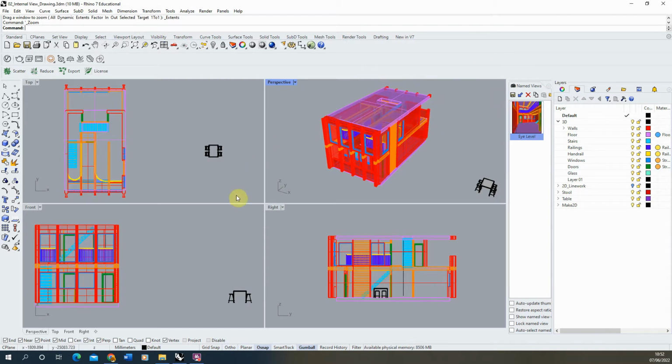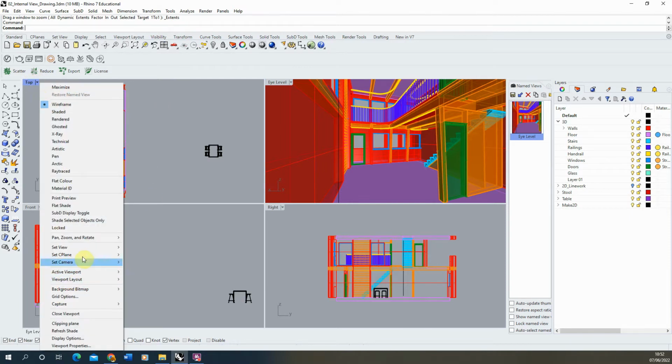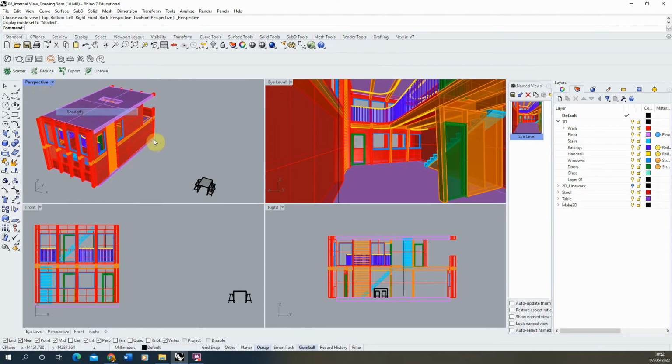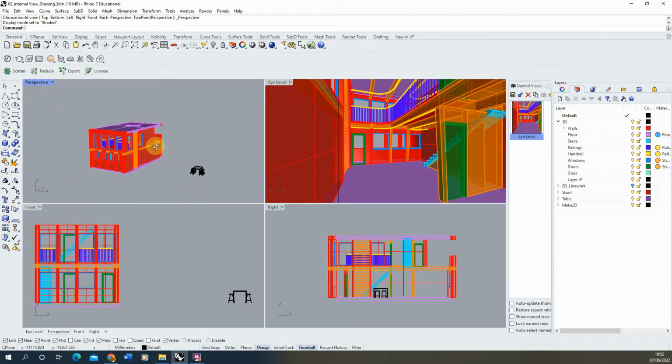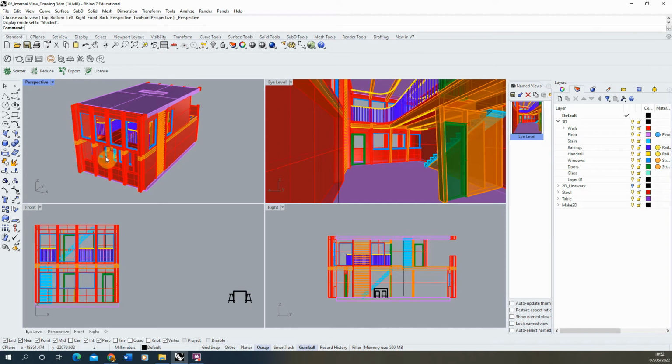we're going to begin by just laying out our windows for the best use to create this drawing. So in this perspective window here, I'm just going to double click on my named view that I've saved to get back to that eye level view that I've set. I'm also going to go to my left hand window here, and we're going to set this to a perspective view, and we're going to make sure it's on shaded as well. The reason for this is that I want to use this view to edit the model and adjust any of the geometry, bring in any other assets into here for my view.